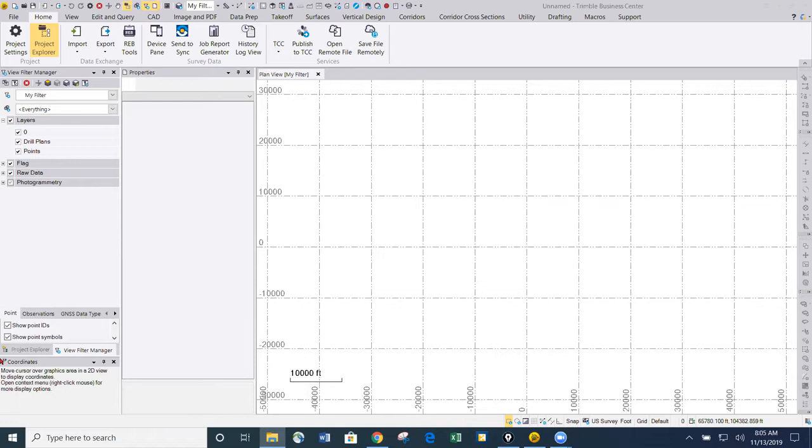So if you, for instance, want to change a slope of 2% to 3% on a cross slope of a road, or from 2 to 2.5%, then it's not just the edge of pavement that changes, but all the other elements that are associated with that. So you have the 4% to the flow line, you have the 1/2 foot to the top of curb, the 1/2 foot back to the back of curb, the 2% to the sidewalk.